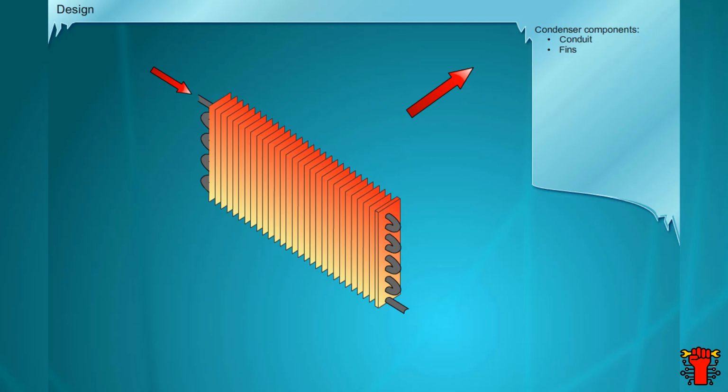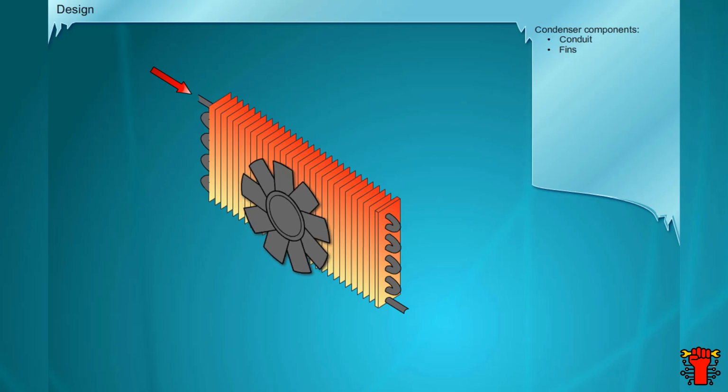The heat exchange works best when the flow of air in the condenser is cool and fast. The effectiveness, when the vehicle is stationary, for instance, is further improved by using a booster fan. Inside the condenser, the refrigerant gas loses heat and then condenses. It leaves the condenser and flows to the fluid reservoir. The condenser is thus dimensioned so that it liquefies the refrigerant safely even at higher outside temperatures.